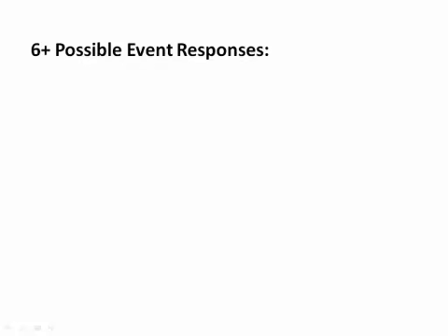Now, looking at ExtendSim, there are 6 possible event responses that have been of use to me. Again, your mileage may vary. The possible event responses are, first of all, I ignore it. That's the last time we'll mention that one, since it's the trivial and obvious case. One event response is that I do not start processing while this event is happening. That means I can continue processing things that have started already, but I won't start anything new.